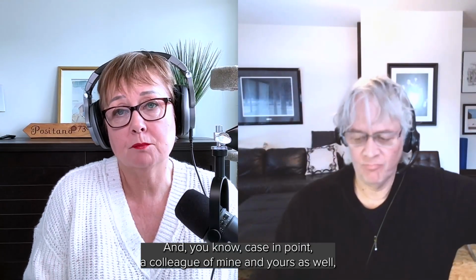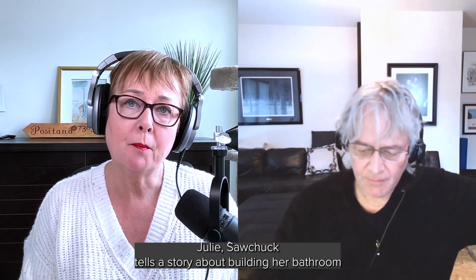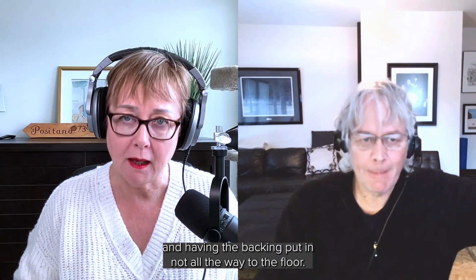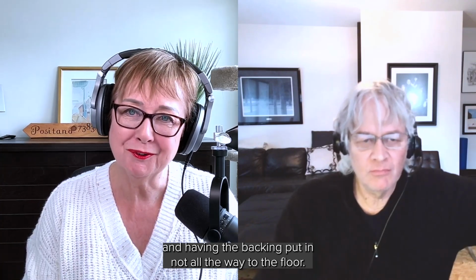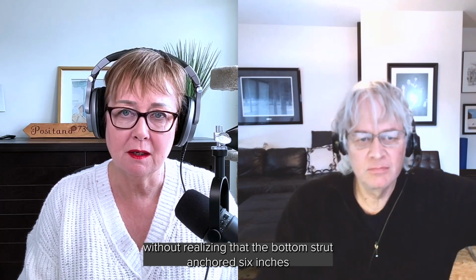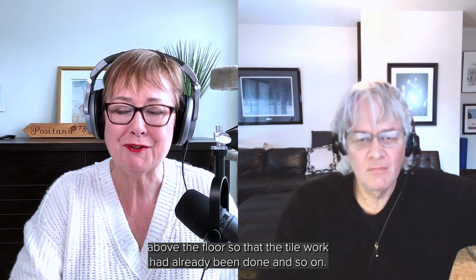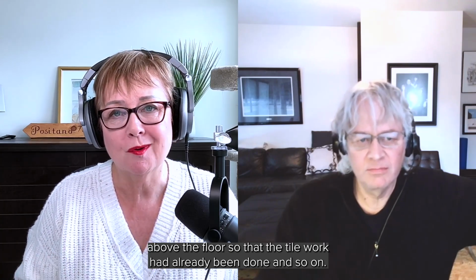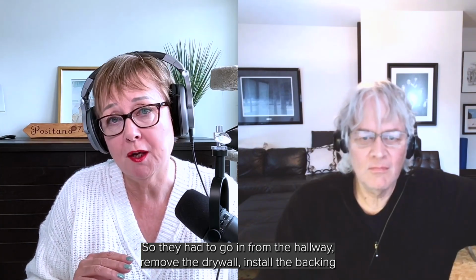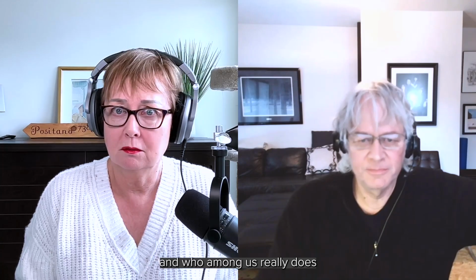Right. And case in point, a colleague of mine and yours as well, Julie Sawchuk, tells a story about building her bathroom and having the backing put in, not all the way to the floor. And then she got a seat for the shower without realizing that the bottom strut anchored 6 inches above the floor. So the tile work had already been done and so on. So they had to go in from the hallway, remove the drywall, install the backing, and then re-drywall. So if you don't know what the future holds for you, and who among us really does, back the whole thing.